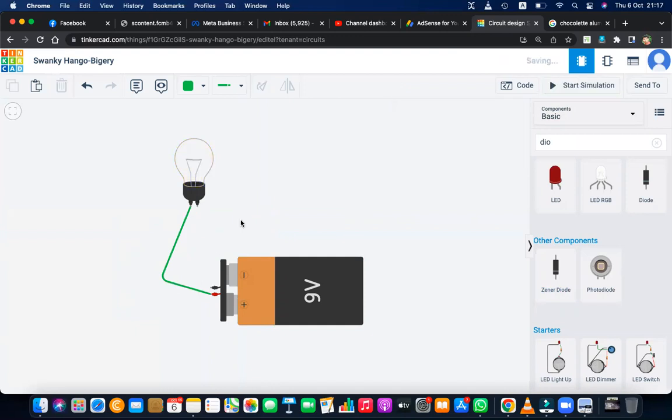So let's use a normal diode. Let's see. Cathode. Anode. Yeah, you can see good light there. Then let's try to change that. Here, can you see? It's not sending the current. It's blocking the current. Earlier it sent the current, but now it's blocking the current. I have connected, but I have changed the edges.